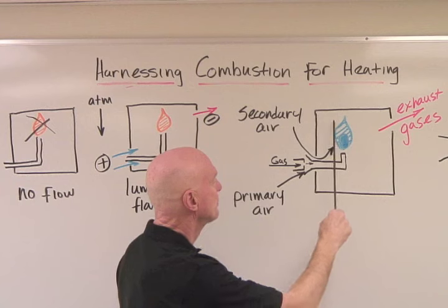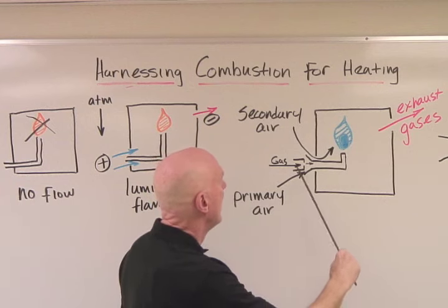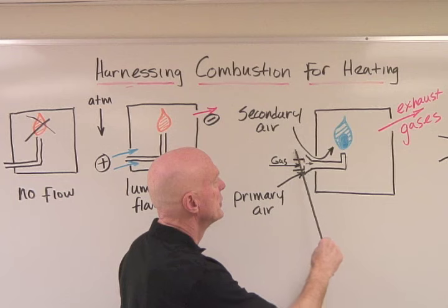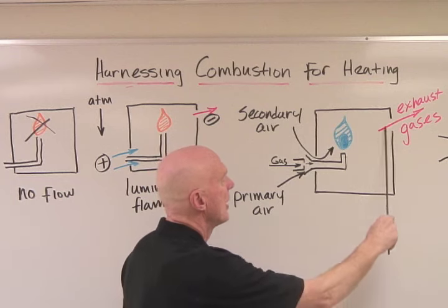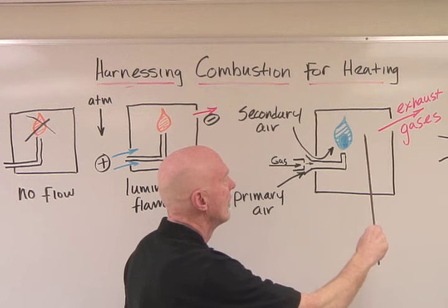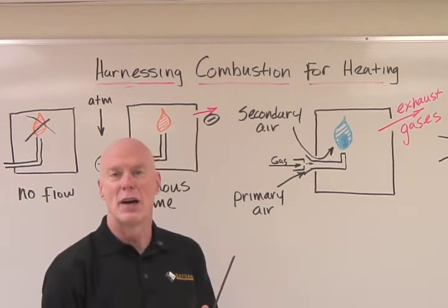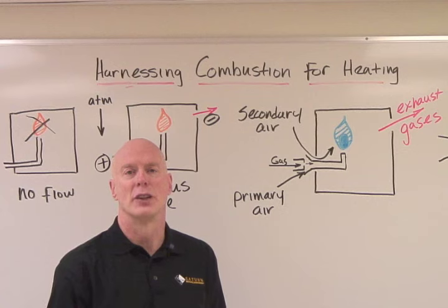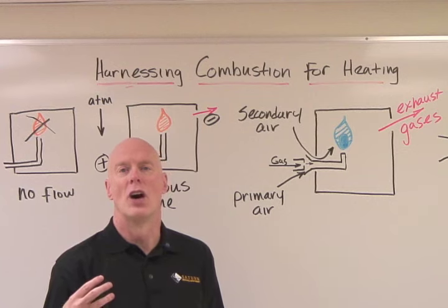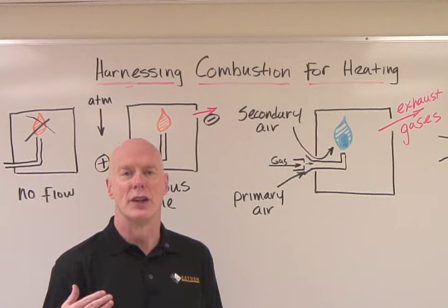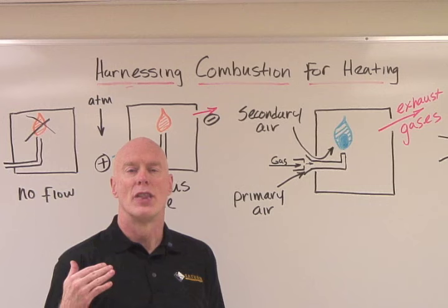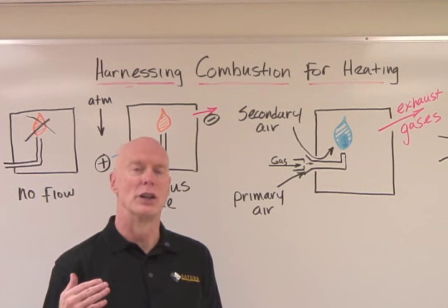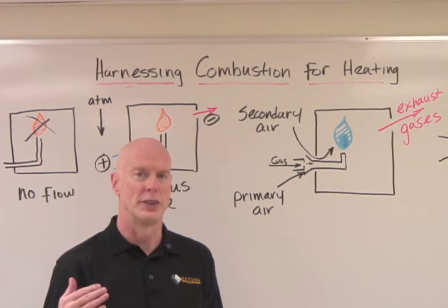this blue flame. And again, we've got a flow of air coming into the combustion chamber and the exhaust gases going out, and that's happening by atmospheric pressure. We talk about atmospheric pressure, but actually we more often talk about atmospheric draft, because that's what we call the pressure in a combustion chamber or in a venting system. We call it draft. We don't call it pressure.